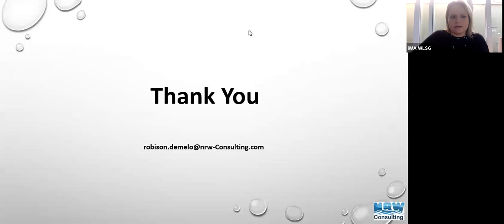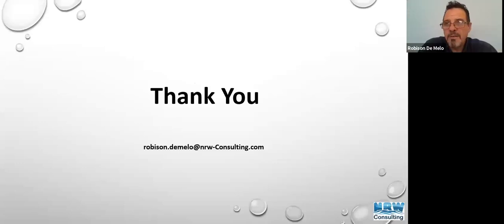That's perfect. Kevin Romain from Trinidad and Tobago is asking, do you have an allowable leakage figure or factor when considering minimum night flow? Actually, by experience, everything that is above 25% when you do the leakage factor is going to be easier to identify, to find the leaks.